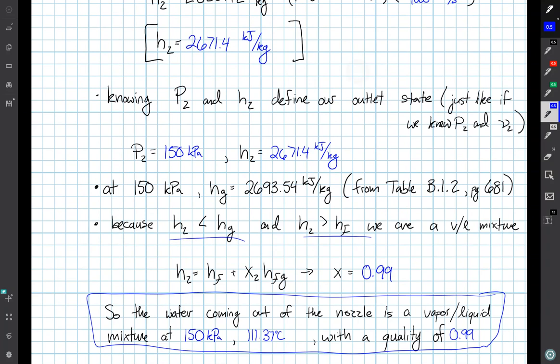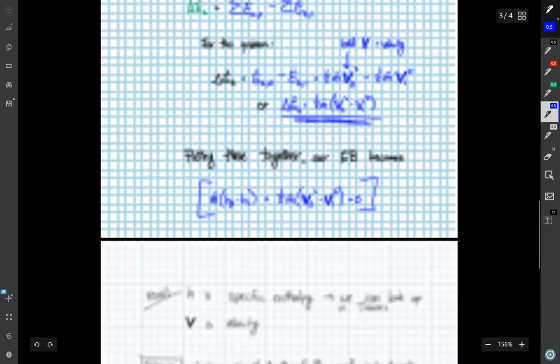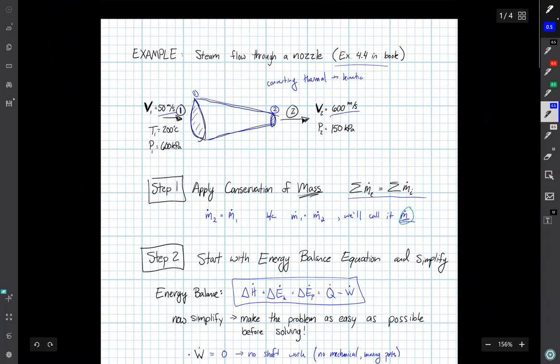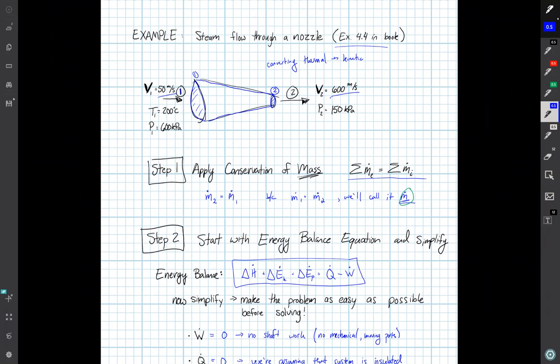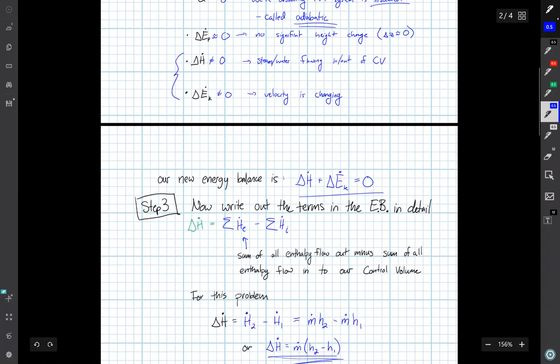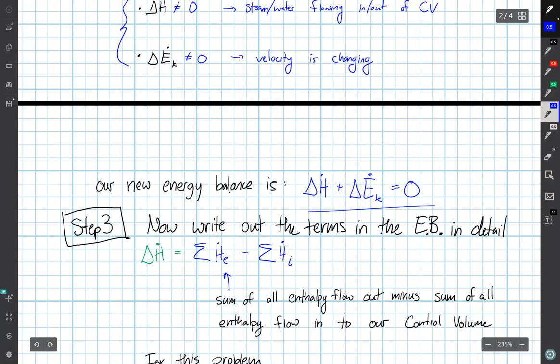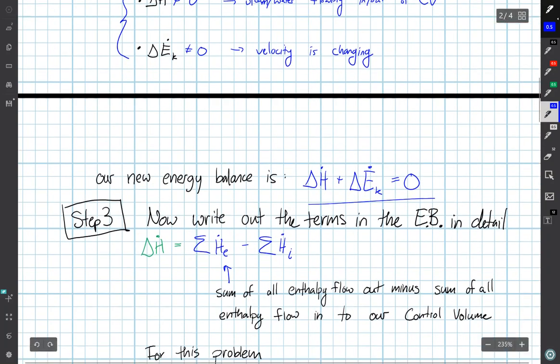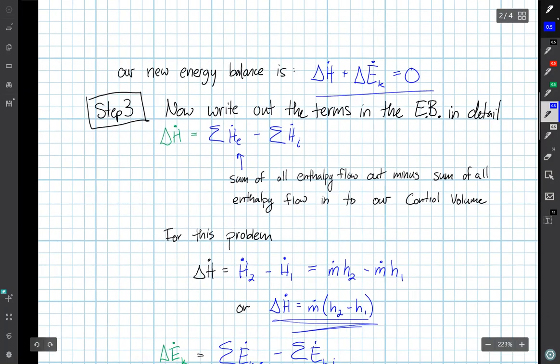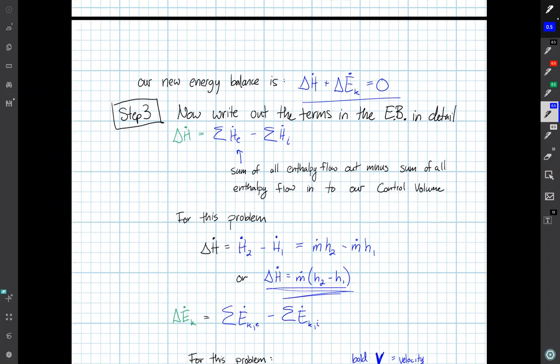Right, if we're thinking about what physically is happening, here physically we're changing thermal energy into kinetic energy in this nozzle. We see that by a change from enthalpy, which is the thermal energy of a moving fluid, into kinetic energy, which is obviously the mechanical energy. That's that velocity change.